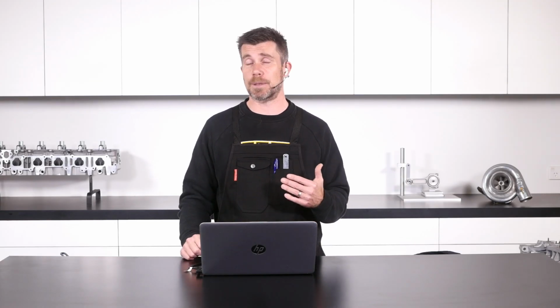Now, if you've looked at any compressor maps, they're relatively straightforward. We've got some other webinars which you can look at on turbo performance that will dive in a little bit deeper and explain what the axes and the islands on those compressor maps are. So choosing a compressor that's suitable for your particular engine in terms of the capacity of your engine as well as your power aims is not particularly difficult these days, and there's some nice tools from the likes of BorgWarner with their MatchBot that will go a long way to helping you with that.